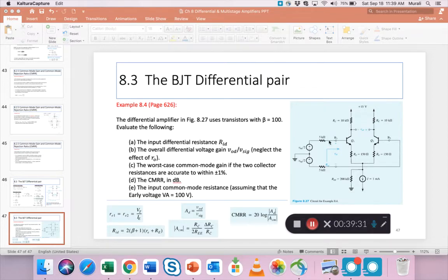But the one thing that I thought was interesting, just the way the circuit is drawn, we always think that we will apply the input voltage, half of it here and the other half here, right? And in the formula, for the input, we use VCM plus half input, and here we use VCM minus half input, right?